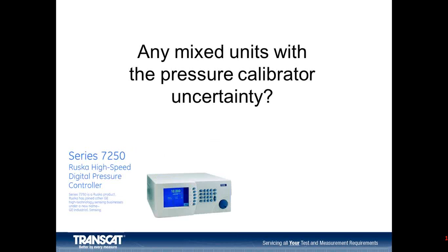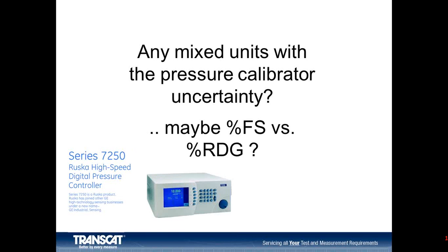Okay, back to the pressure indicator. Are there mixed units of measure with the pressure calibrator? Well, certainly there are. For the laboratory grade instruments, typically a multitude of unit conversions are available. But that typically doesn't affect the uncertainty, assuming that the conversion factors are correct.